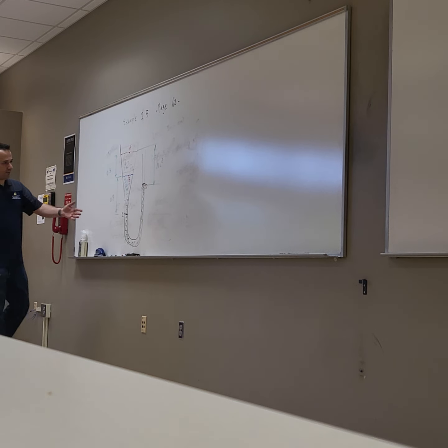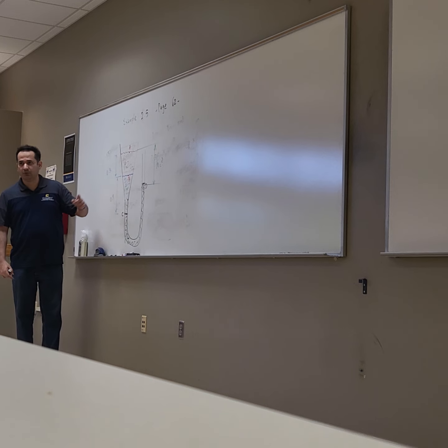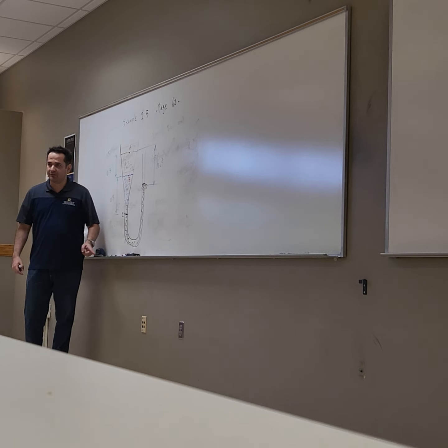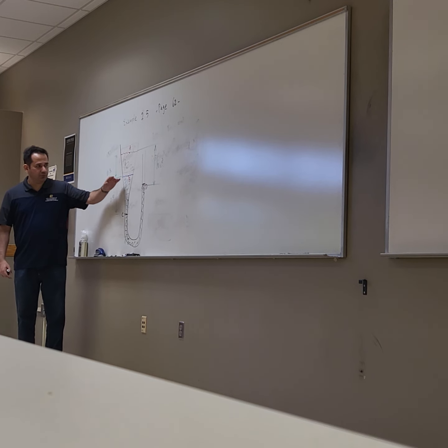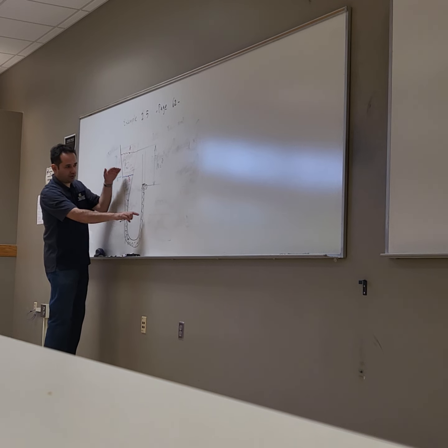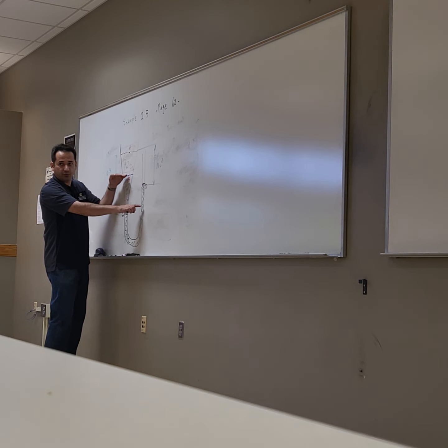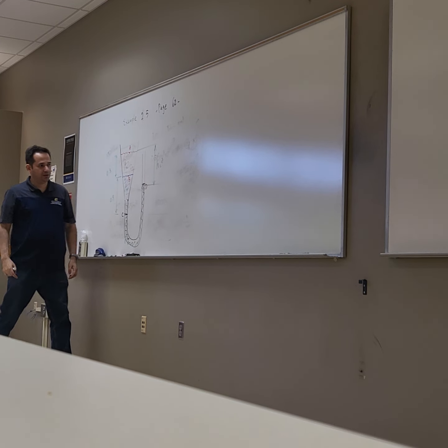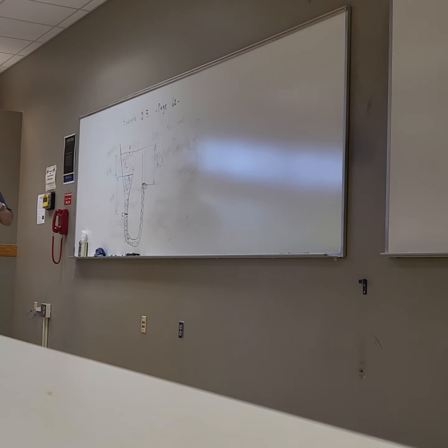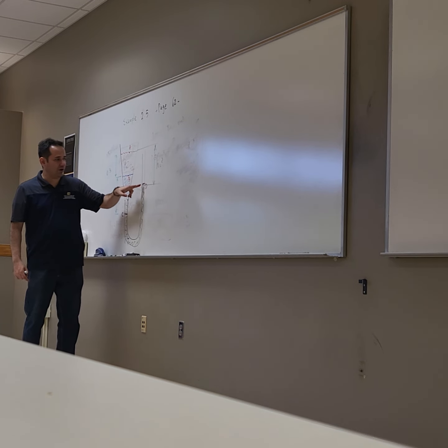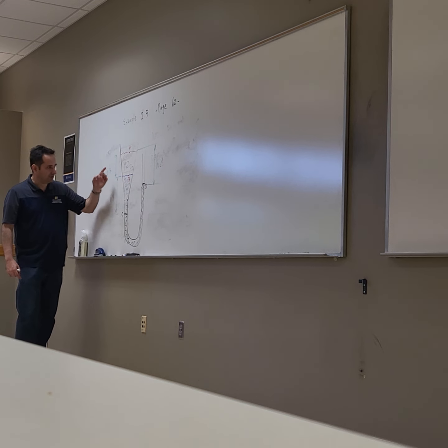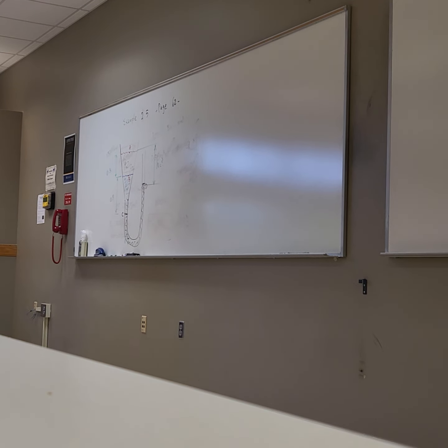Right? So in this configuration, we have a U-shaped tube connected to the cone, and here we have mercury, and the density rho Hg is given. Then we put a little bit of water on it, so this height will go up and down a little bit, and then we put a little bit more oil on it, and it goes into this configuration, right? And we want to compute H, the surface height between the mercury and the oil. All the rest of the densities are given, and the other heights are given. You can measure that in the lab.